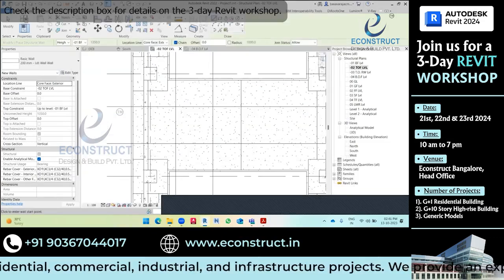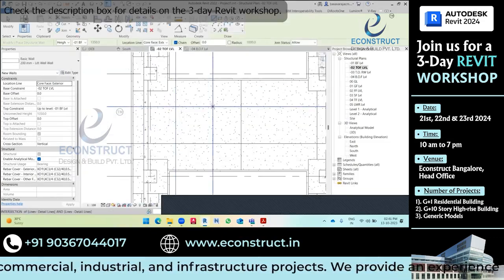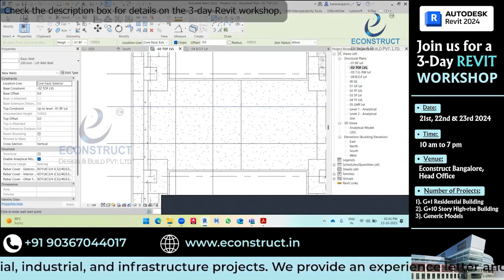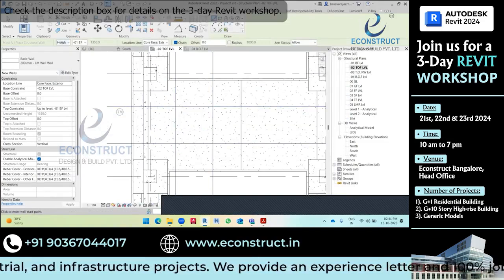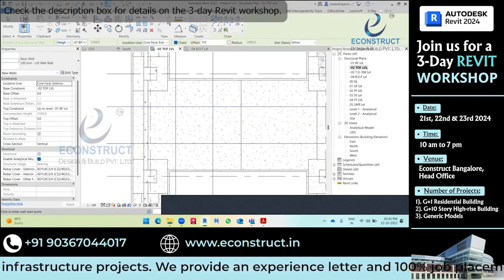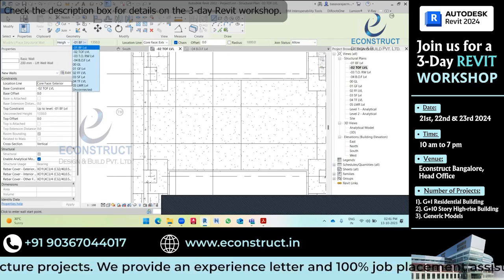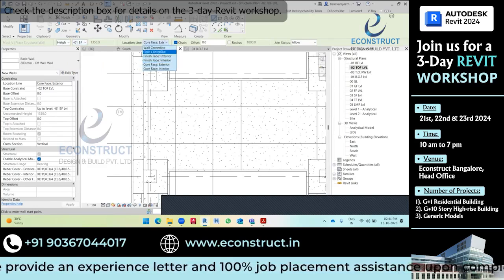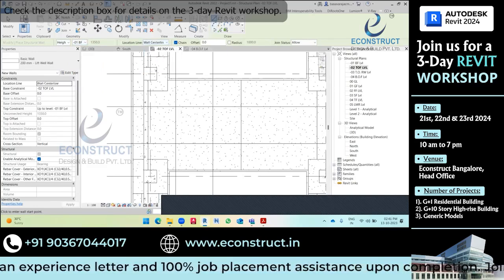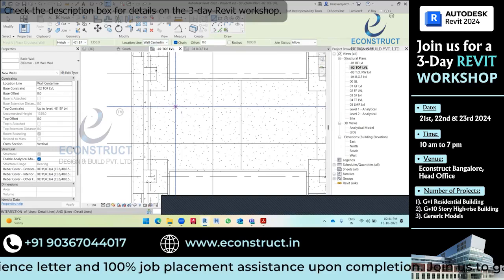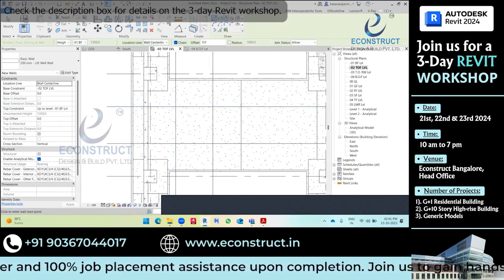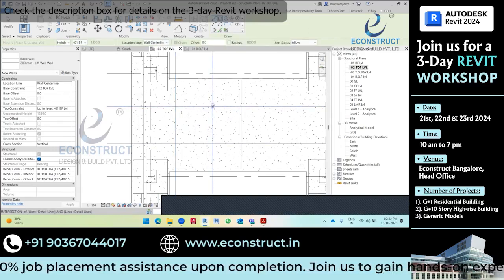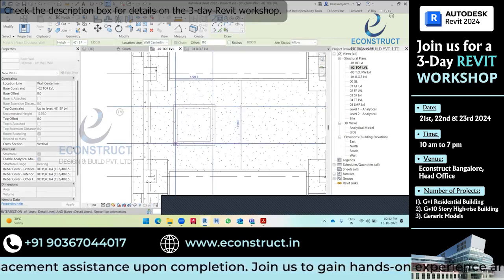So now this is the center line of that wall, right? Select the height for the wall, and top constraint is basement floor level only, and for location line, instead of core face exterior, take the wall center line. Then you can draw like this with the help of the line tool, or select the rectangle and just draw the wall like this.